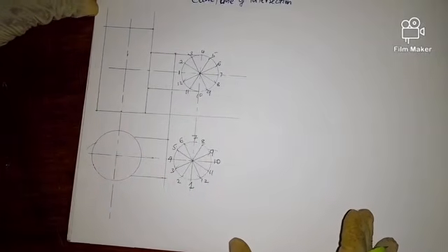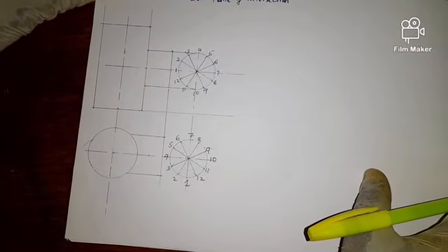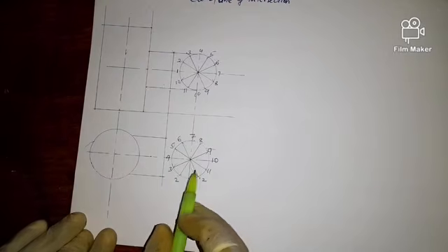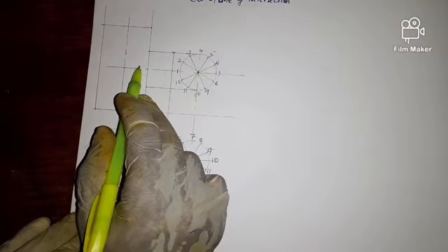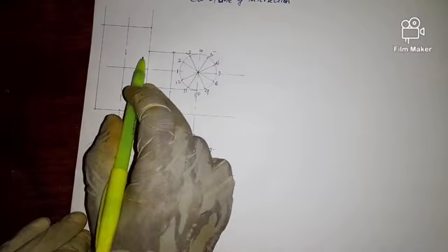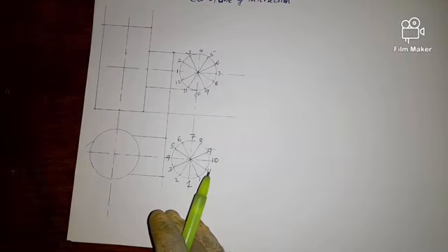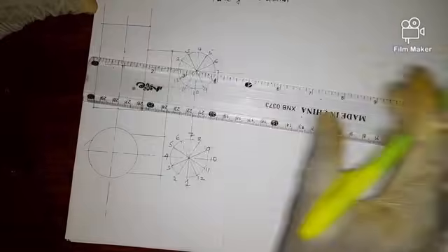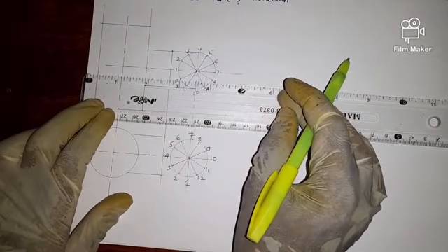Next thing we shall do is draw our curve of intersection. For us to draw a curve of intersection, we draw horizontal lines to come from this end, and they meet lines from the other end, somewhere where they intersect. It gives us that particular curve of intersection. So let's draw those lines horizontally. The first one is this.